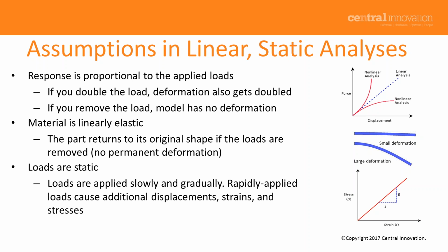Therefore, the first question you always have to, let's say, answer is, what is my material? What sort of loading do I have? If it's fitting to linear static, that's why you can choose the linear static in SolidWorks Simulation Standard. So if the assumption is false from the beginning, for example, you have rubber rather than steel, then there is no linear here.